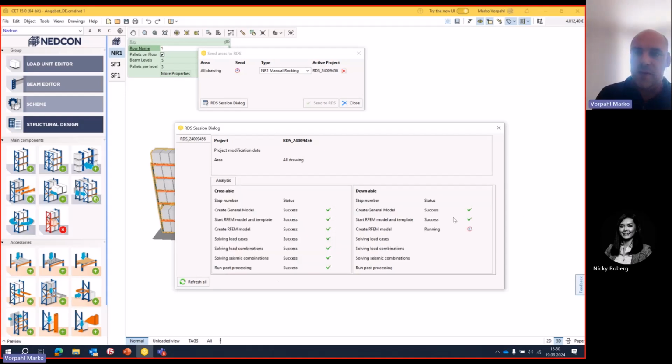And all the hooks that you see are green here. If you think, yeah, I have made the right combination of profiles and beam types and so on, no. It only shows that the calculation ran well, or it's finished and ran successfully. That doesn't mean that I have chosen the right profiles in the end. The first time, most people say, hey, I have everything right, but no, it's not right.